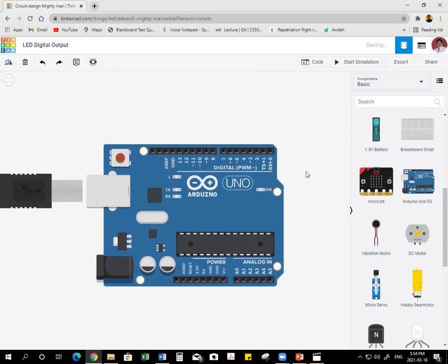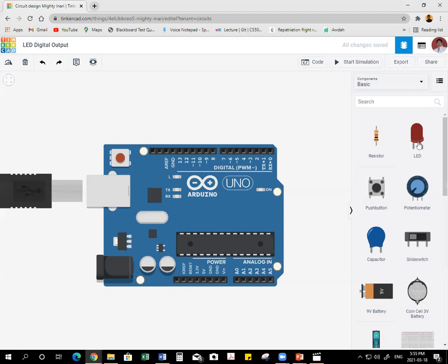Now what do we need? An LED. Now, digital pin 13 is directly connected to the LED. It can glow directly. No need of any basic programming, just 1 or 2 small blocks. See here, I just brought the LED here, so I will put it on the top. Yeah, so red. Okay, no problem. Now connect this cathode to ground.